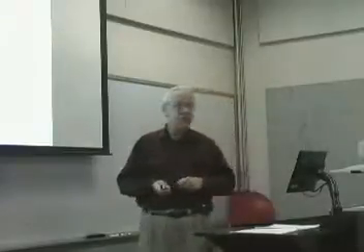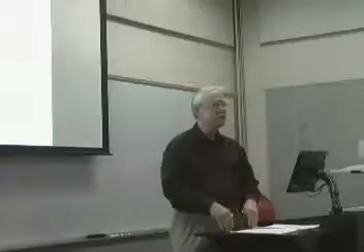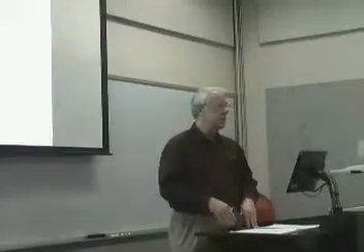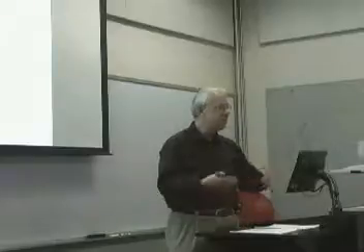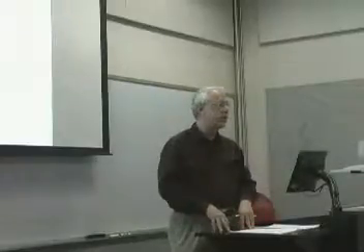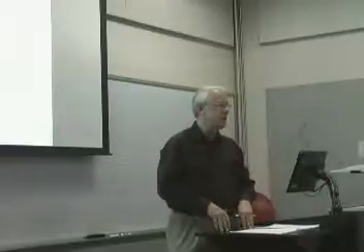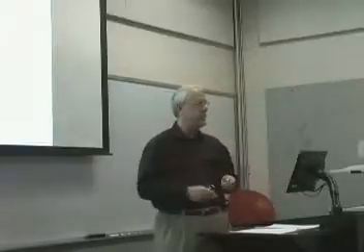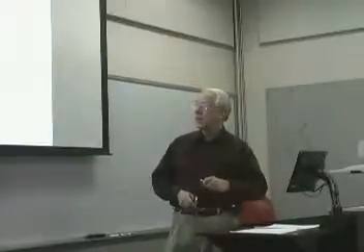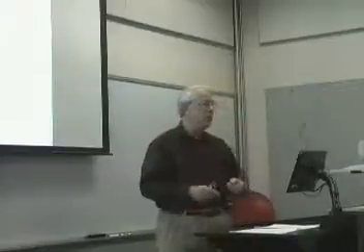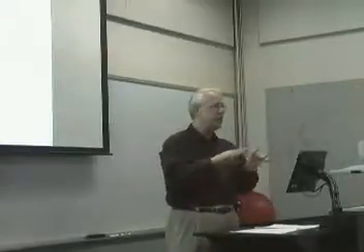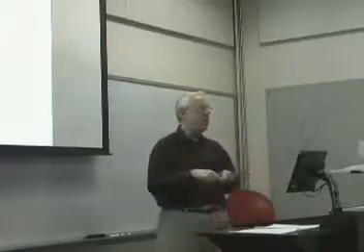Now that equation, because I'm doing an approximation, is not actually equal to 0. Why is that? Because you're doing an approximation. And by doing a computer approximation, there's always a residual, like a Taylor series. So there's always something that is not exactly equal to the original equation. Does everybody understand? So that means that equation is actually a residual. So I'm going to multiply a weight, I'll tell you what the weights are in a minute, times the residual, and I'm going to set that equal to 0. So what I'm doing is distributing the error throughout the entire computational domain, or the problem domain.